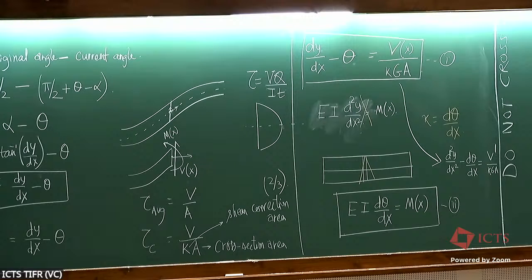No, this is also not true. See, we could work with this formula for curvature only for EBT, even the nonlinear formula. Because this is eventually the curvature of the center line. This is independent of how two cross sections here will pull or push.